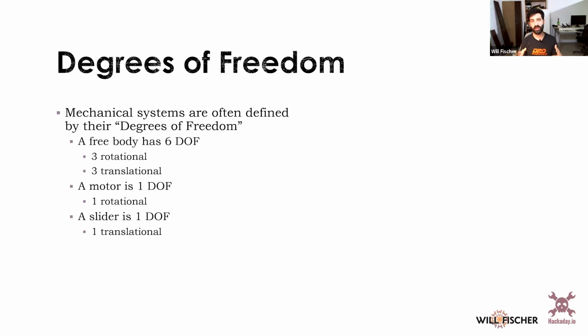And so to try and get smooth motion out of them, you need to think about it like, okay, if I need to be able to rotate this thing and translate this thing, those are 2 different degrees of freedom. I'm going to need 2 different actuators, because you need an actuator per degree of freedom in order to get them to operate independently.